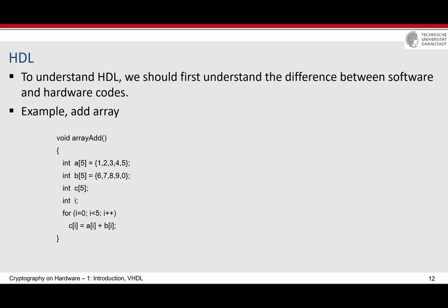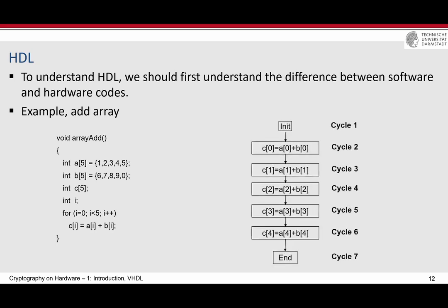if every addition takes 1 clock cycle, which is usually not the case. If you have a microcontroller, usually this addition may take longer than 1 clock cycle. It depends on the architecture of the microcontroller. If you look at super old microcontrollers like the 8051, every such addition takes 12 clock cycles. If you look at the ARM processors now, because of parallel processing and pipelining, roughly on average you can say every addition takes, for example, 1 or 2 clock cycles. Now, this is what we discussed, a couple of cycles.